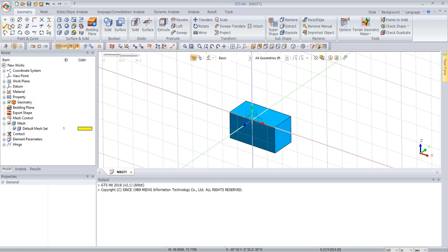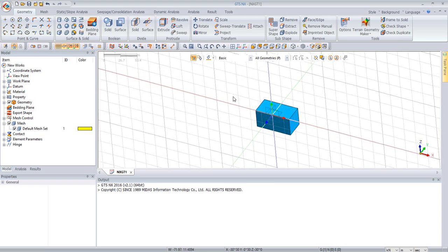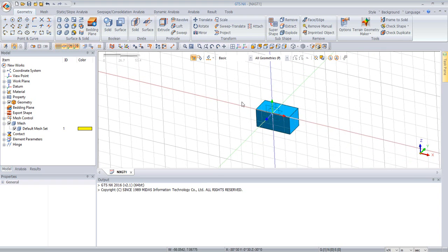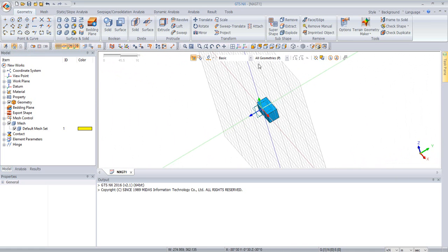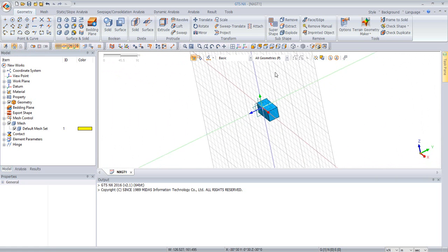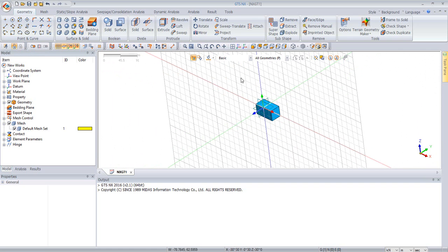Now we're going to draw the location of the pile. For things that are 3D solid geometries, you can drop them anywhere you want. But when you're drawing 2D, we have what this is called, this work plane. You can kind of see that it's here on the ZX plane. So if I want to draw something, it's assisting us since we're working in a 3D environment. It would be very hard without something like a plane to draw something two-dimensional and be able to distinguish the depth of where we want it to be. So this plane helps us for that.